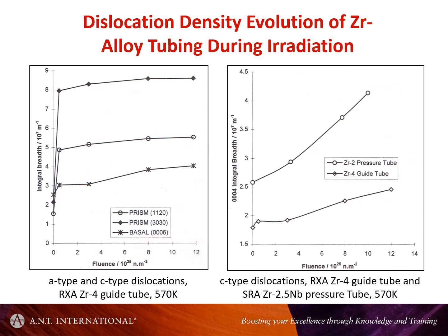On the right-hand side here, I'm comparing this breakaway condition again as a function of fluence, and comparing with what you would see for an equivalent material, in this case stress relief annealed. That's not a zirconium pressure tube. In fact, this is for a Zircaloy-2 pressure tube. So that's an error. I'll have to change that. Apologies. But a Zircaloy-2 pressure tube taken from the SGHWR in the UK, after it broke down, I was able to get some samples and examine them.